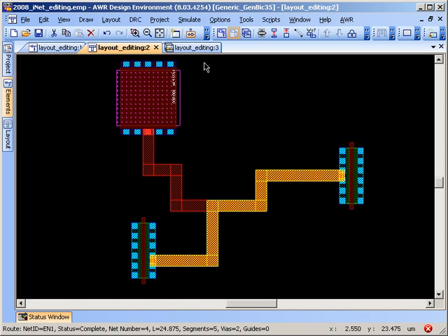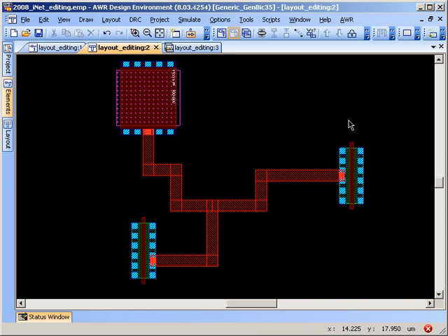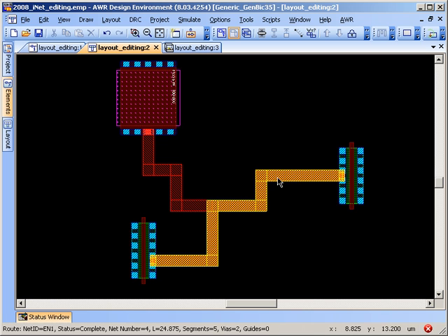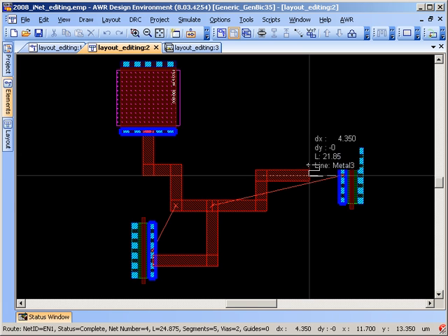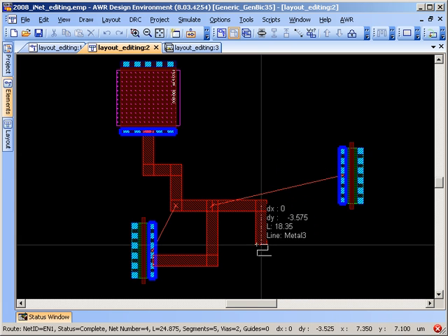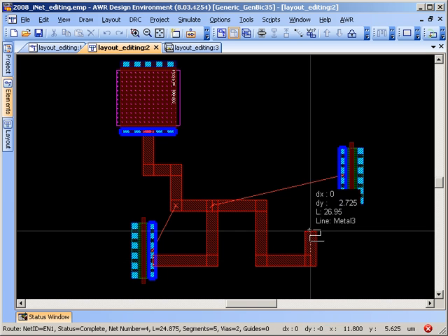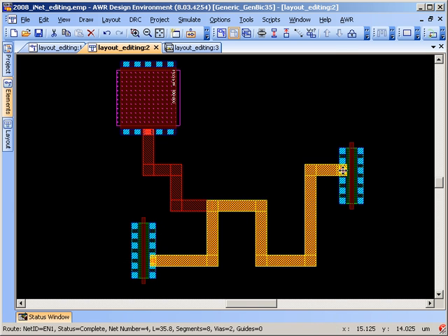And then the last new feature for this video is the slice command. We had always had the slice command for what we call dumb polygons or dumb paths, but it didn't work on the intelligent nets, the iNets. So now this is enabled for these layout objects. So I'm going to demonstrate this. I'm going to back this route up a little bit and meander it to show how this feature will work.